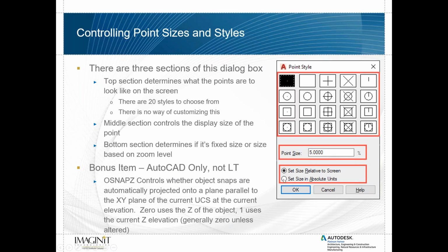The bottom section determines if it's fixed. So if I set this as Set Size in Absolute Units, whatever I specify here for the point size will be absolute units in the drawing, no matter what my zoom level.